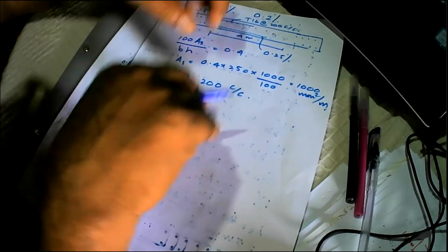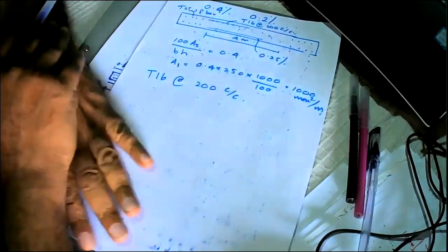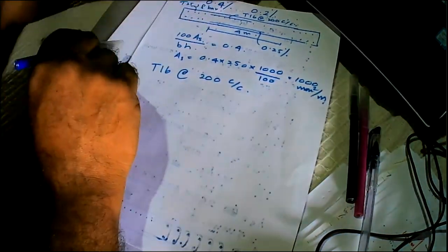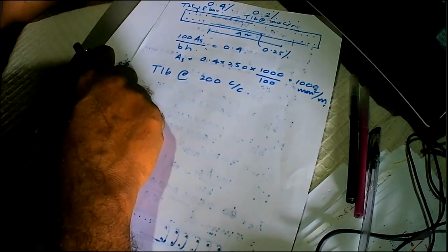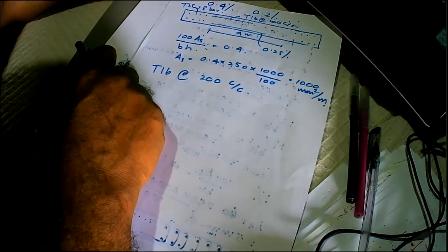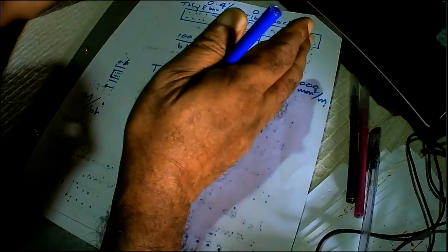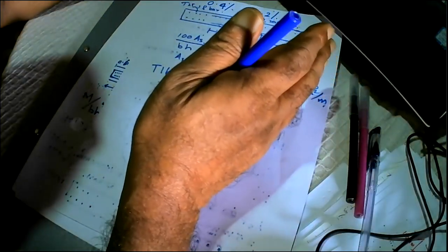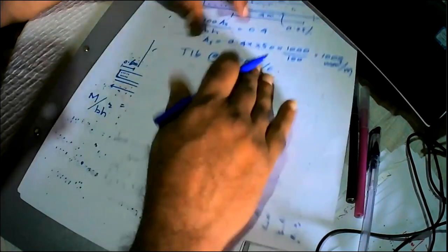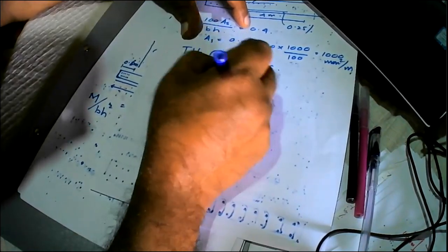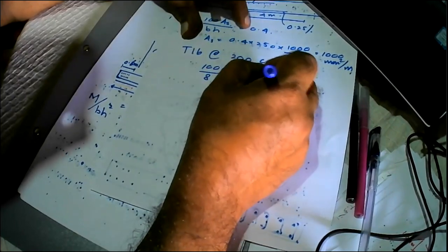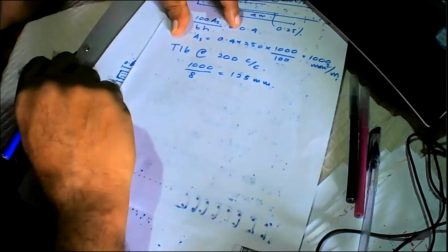But generally, when you are taking this confinement length, you have to take a reasonable distance. So you can see for this 1 meter, this D/C ratio remains around 0.91, right? Yes. Because when I am providing 8 numbers of 25 millimeter bars, I need a reasonable length. 1000 millimeters divided by 8 bars means the bar spacing will become 125 millimeters, right?